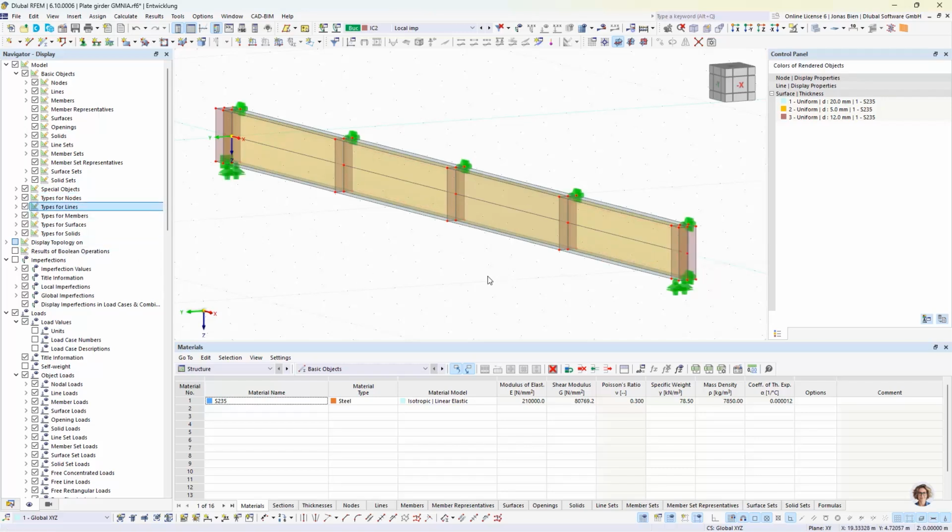Okay, so now the last question is, how do we combine all these imperfections together? In Eurocode 3 part 1-5, we have a combination rule for equivalent geometric imperfections. We have one primary imperfection that we assign with 100%, and the other ones we take with 80%. But just to make things a bit simpler here, I would just take them all with 100% amplitude, because in most of the cases, there's always 1 or 2 imperfections that are not really relevant or critical for the end result.